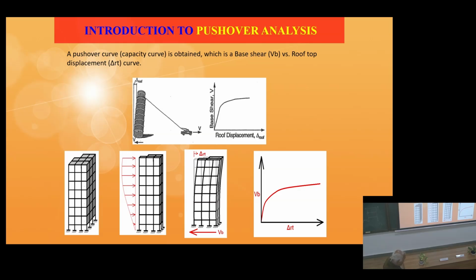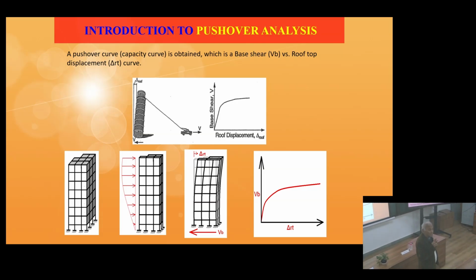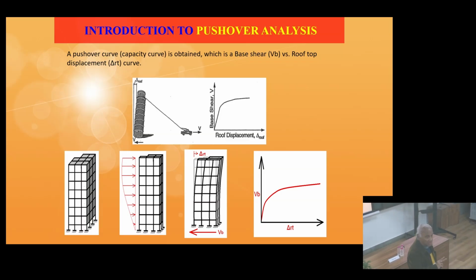So this is the pushover analysis. We push over here, and we will see later in the slide there are two types of pushing or pushover analysis. One is force based pushover analysis, the other is displacement based. Right? And what you were learning yesterday, the last 2 days, was displacement based design. Okay, that means the pushing is basically based on the displacement, not force.